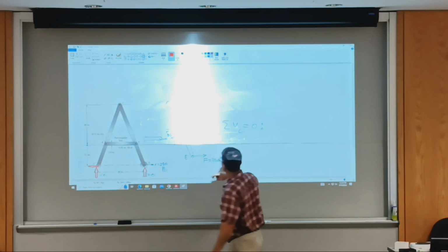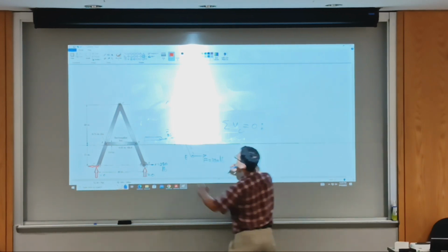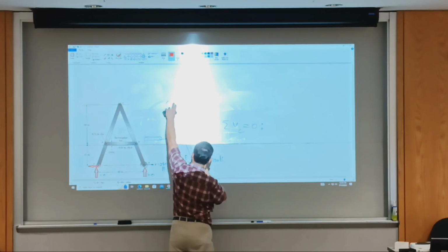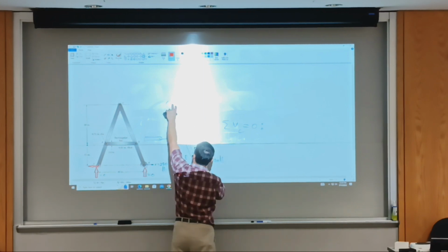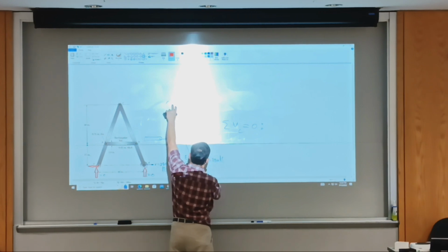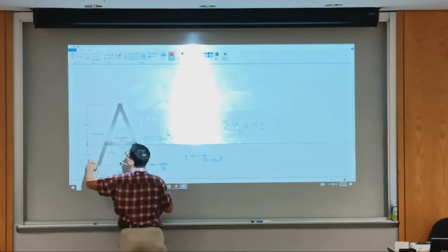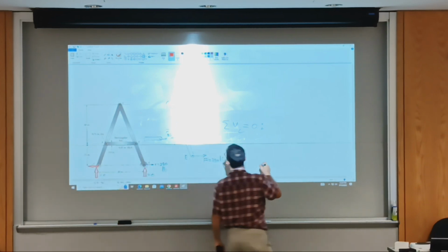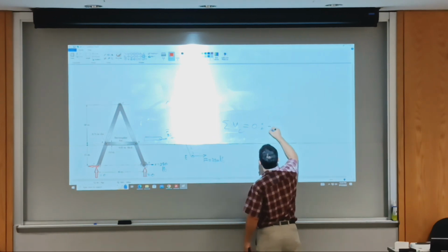So if I begin from the bottom, I put my finger there to mimic a pin about which the beam is rotating. So I have F times, or 2,800 times 15 plus 30, that's 45. And that's positive, just because of my choice of positive for moment.